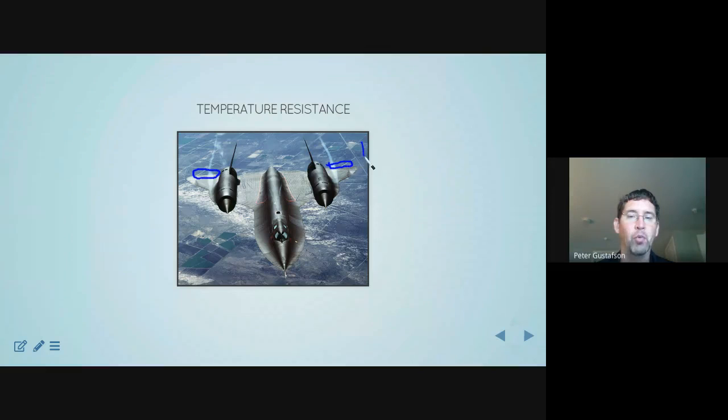And what happens is as you're trying to roll the aircraft, one of those deflects up, one of those deflects down. It changes the lift on one side. So the side that goes up actually decreases the lift. It creates a downforce on that side. On the opposite side, where the aileron goes down, it creates a force up, increasing lift. And that's what rolls the aircraft. That's how most modern aircraft control roll of the aircraft. So that's turning left or right in the aircraft. That's what an aileron is.